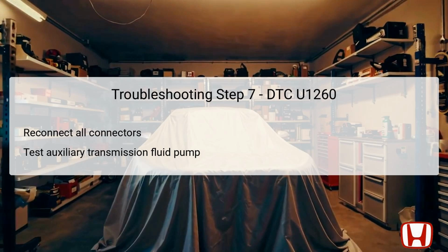Conversely, if the pump fails to operate correctly during this step, it confirms that the pump is faulty. Consequently, the pump would require replacement to restore normal function and resolve the diagnostic issue indicated by DTC U1260.